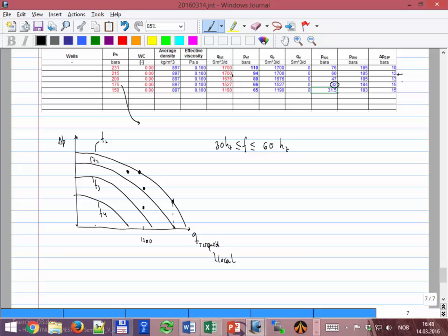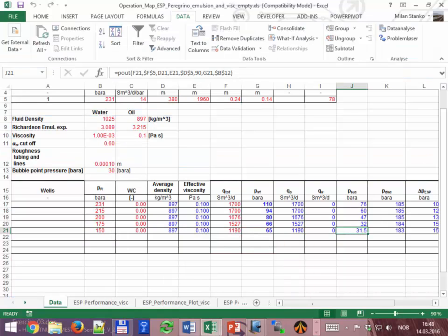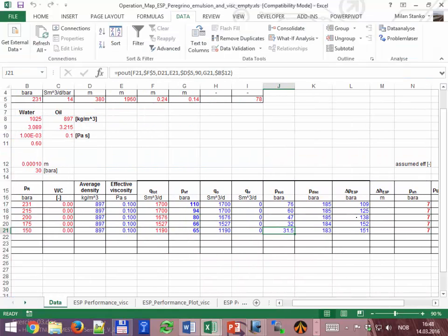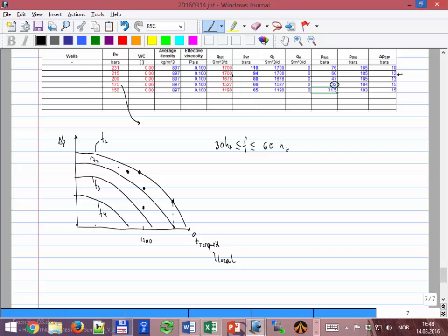Delta P of the ESP, yeah, I took it away. That was very smart of myself. 150, okay, remains more or less constant for the last 2 points, but the rate is reduced. Okay, so we think it's going to look something like that. Just constant first going up, then I reach the limit in power, and then I have to reduce because I reached the limit in suction pressure.